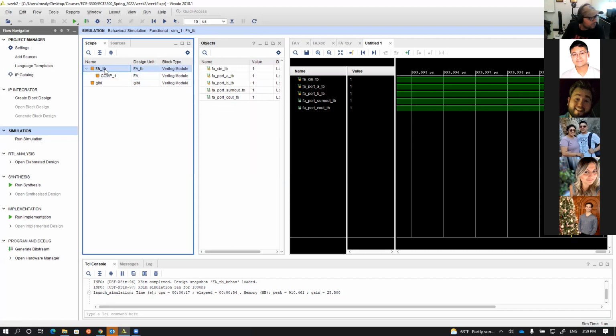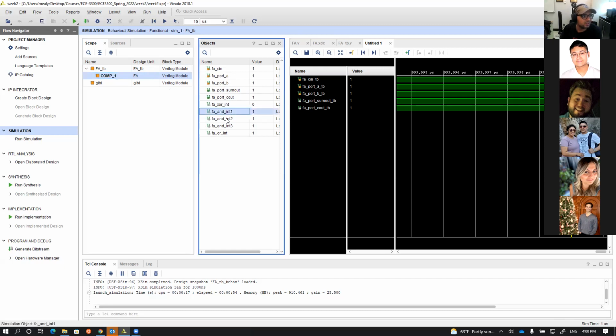If I go up here, it will give me all of the signals of the TB. You guys agree? So that can help me to do what? For debug. If I would like to debug what's going on with my code, I don't care that much about the ports. I care about what is internal, so I can see what's going on. If you remember, we have the intermediates of the AND, OR, and so on, so you can propagate and see whether your code is correct or you connected something wrong. Sounds good?